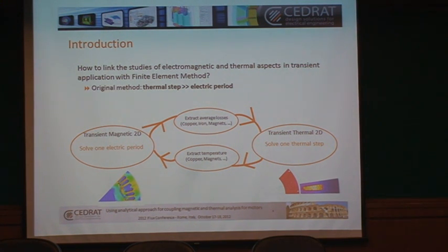But for the thermal, if you really think about it, I only need 1 pole on the rotor, since this is a brushless machine. And I need only 1 slot. I don't need all the slots. One slot is going to be enough, because over a full cycle, all the slots see the same power. The average power in each of the slots is the same, and the average power in 1 pole on the rotor side is the same over a full electrical cycle.